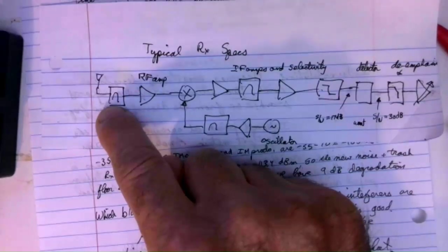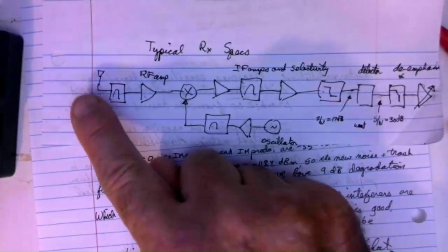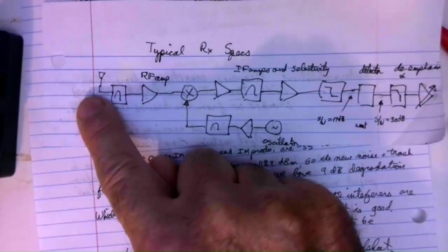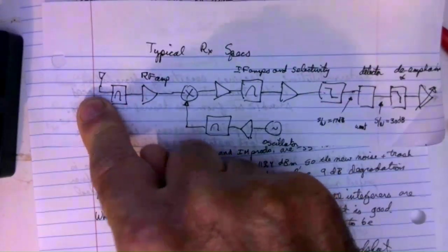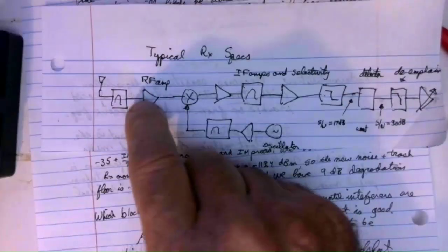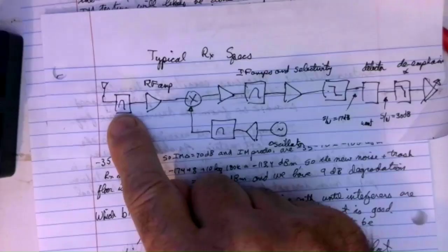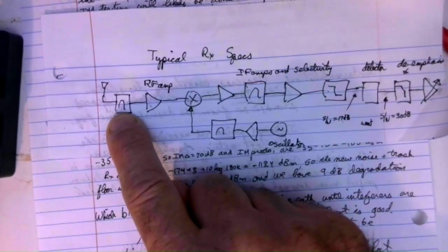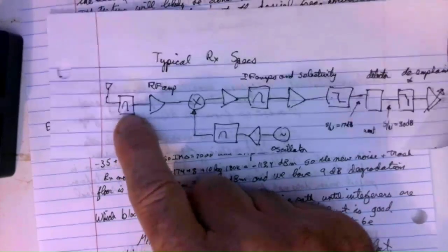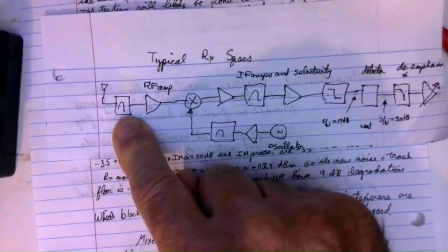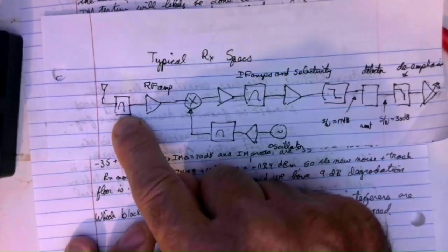Never mind the fact that if you don't, all you have to do is walk up and touch your receive antenna, static zap that receiver front end, and then that's it. Then it's done. So this guy right here is important, and it reduces your probability of getting creamed by things you're not even thinking about. It's good design practice. Band limiting if possible. Band limit everything if possible.